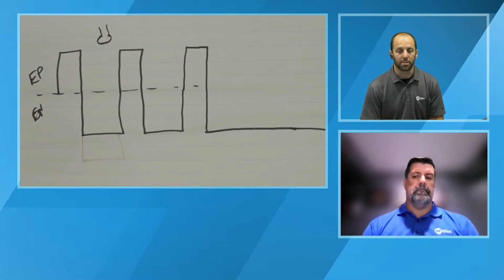Anodized aluminum is essentially a mechanical or chemical process of increasing the thickness of that oxide layer to an intended level or a predictable level, at the material manufacturer. And like you said, that's done primarily for corrosion resistance purposes. Where we see it utilized the most, handrails. It's mostly tubing, so handrails.